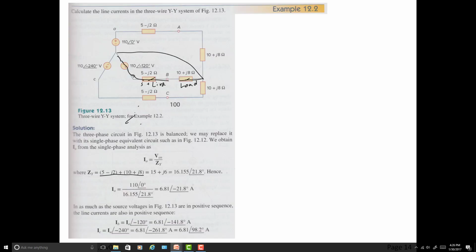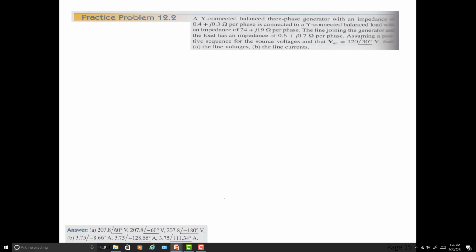This is reduced here into some very complex phase shifted Z. We haven't done that before. We've been comfortable with 30 and 60 degree things. And so the current is simply the quotient of those two, so a small value and this really odd angle. Okay? But once you have that, the 120 degree phase shifts easily gives you all the rest. So I don't think I need to say much more about that.